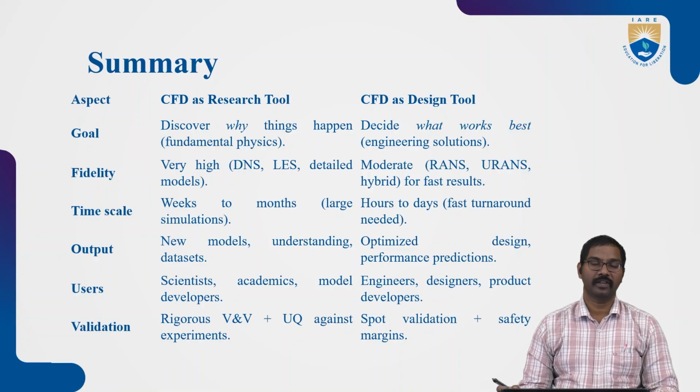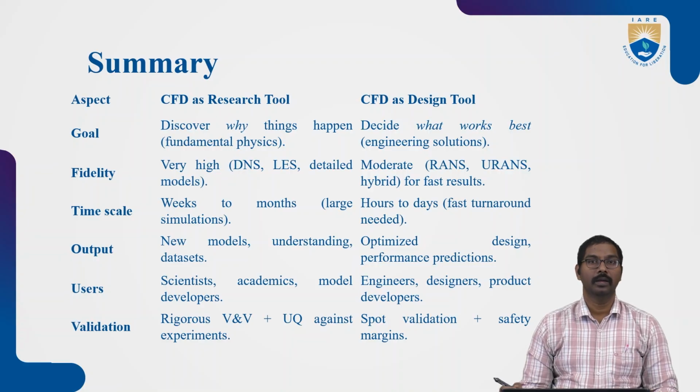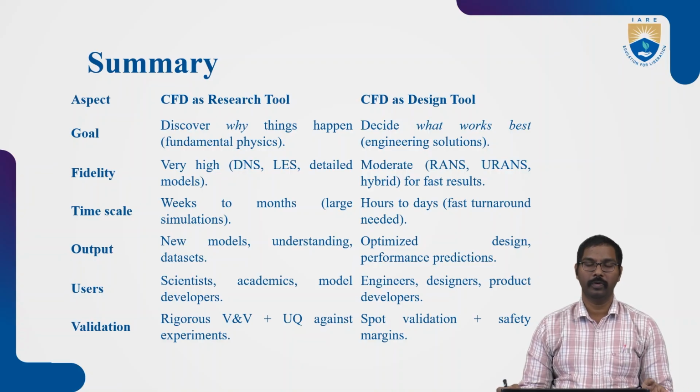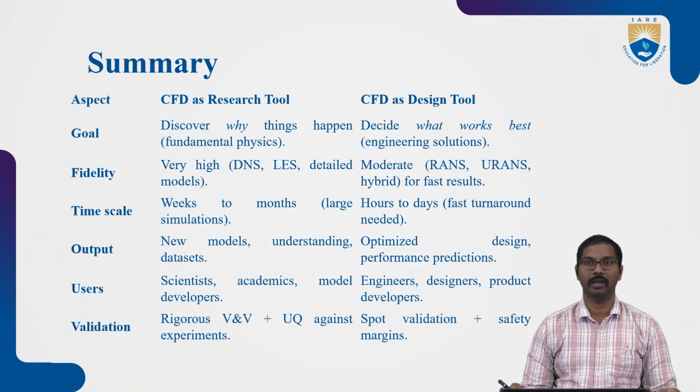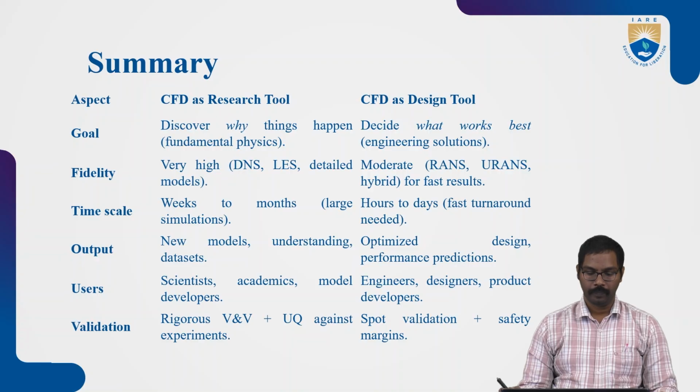CFD as a research tool has very high fidelity, because of using DNS and LES and detailed models, or more developed models as per the problems. Whereas in the design tool, we use moderate models, RANS models, to get the solutions accurately.